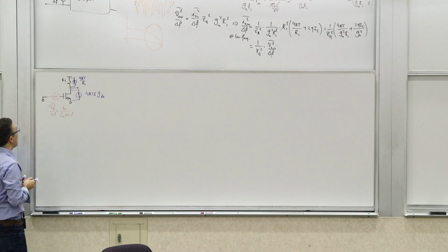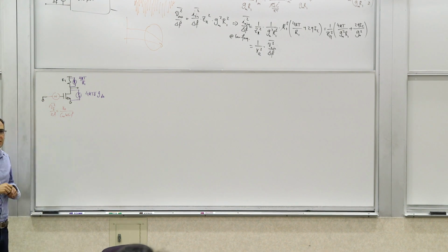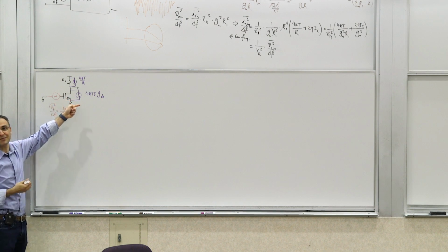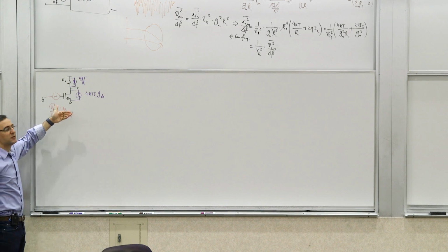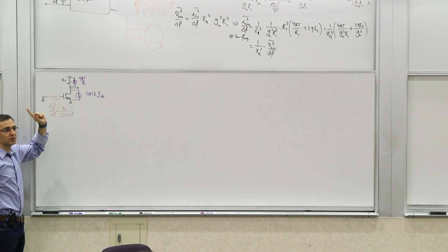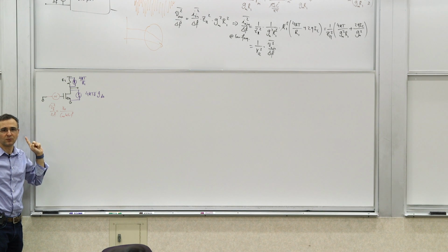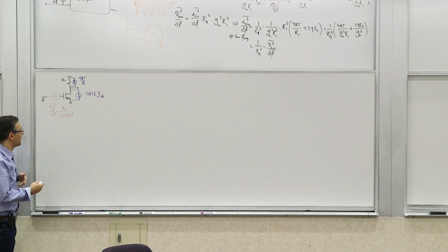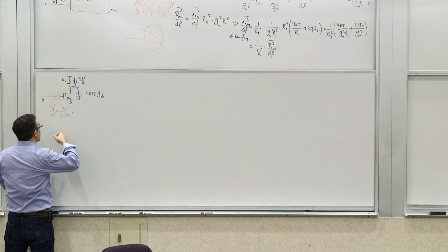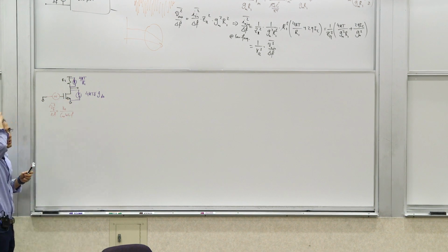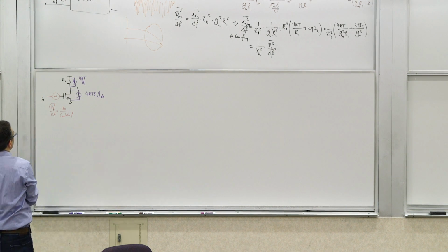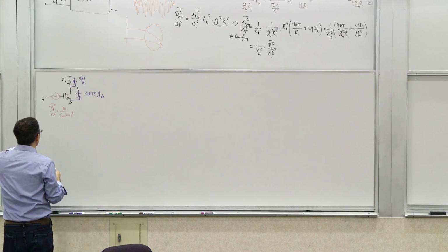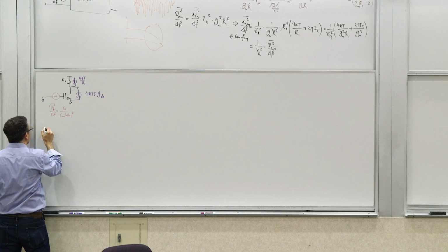noise, for example. Now, if you're looking purely at low frequency stuff, the input impedance for a MOSFET is a special case because it is infinity at low frequencies, which basically means that an input referred voltage source is sufficient. If you're looking in general at some Z pi, it can be at CGS, then you need to take that into account, and basically there's a transfer relationship that we calculated before between the input referred current and voltage. But let's just quickly calculate the input referred voltage source. So V in squared over delta F.